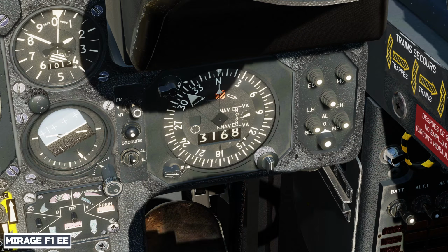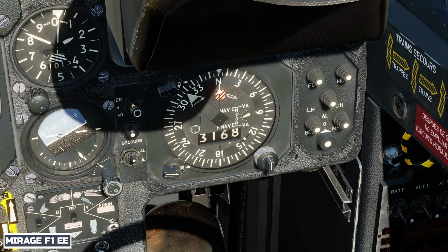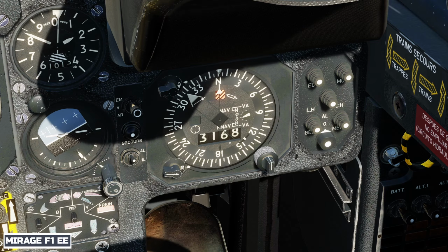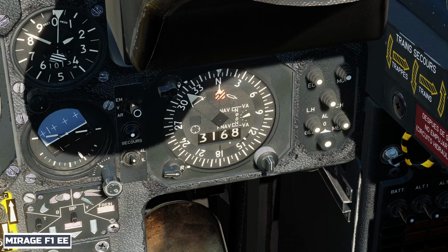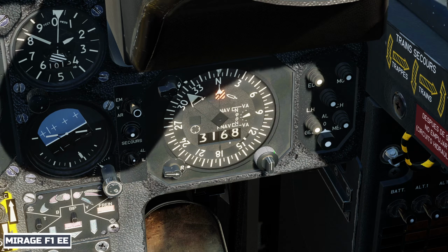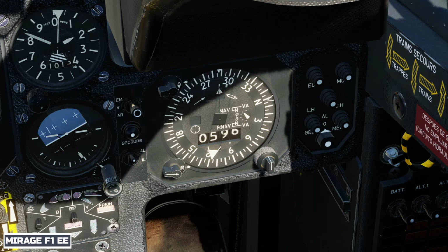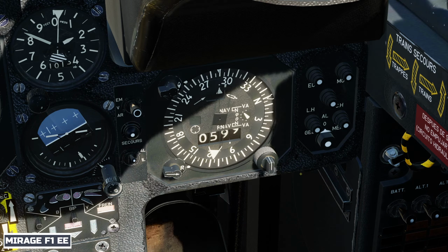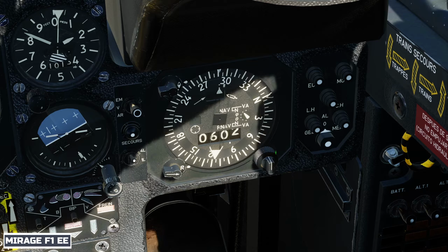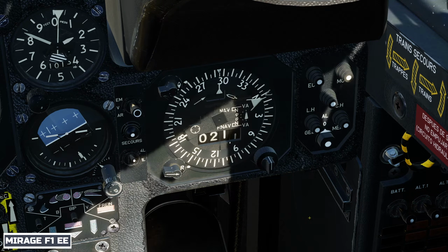With the offset value set, we can then display the navigation cues on the IDN to the offset location by setting the IDN's mode to Nav VA, INS Navigation Additional Vector Mode. Nav N mode points towards our INS waypoint. Nav VA mode now points towards the offset location.